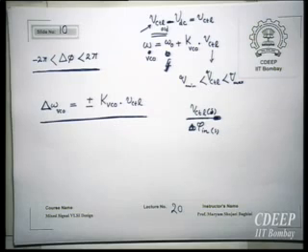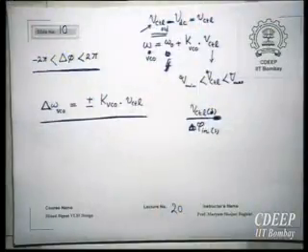So, what is the maximum change in VCTL I can generate? It depends on the charge pump. Suppose the maximum change in the VCTL I can generate is due to this delta phi if I change the input frequency, not phase. If I change input frequency, PLL also now will go to a new frequency with a second order system response.